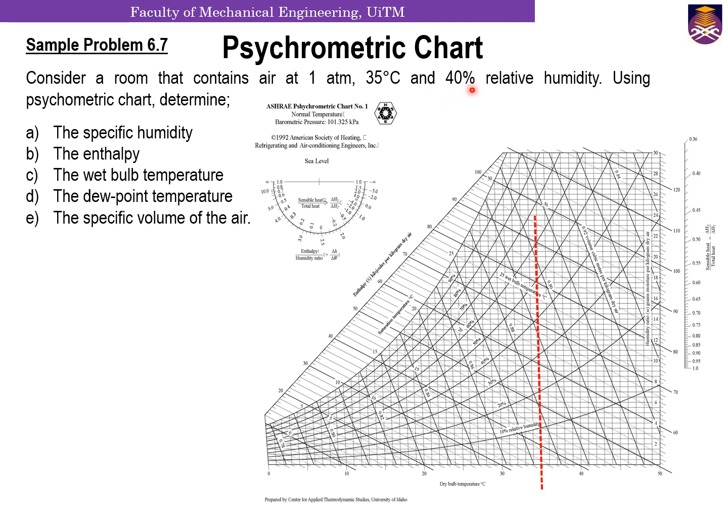Then we find what is our relative humidity, 40%. So we have, these are the relative humidity lines. So 10% is here, 20, 30, 40. So this is the line that represents 40% relative humidity. So that will give you an intersection point here. So that is your intersection point as shown as the blue dot there.